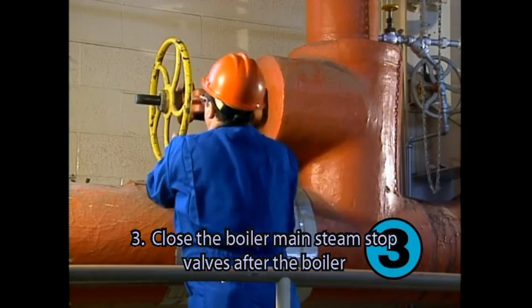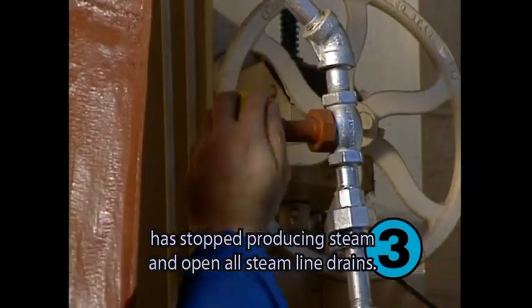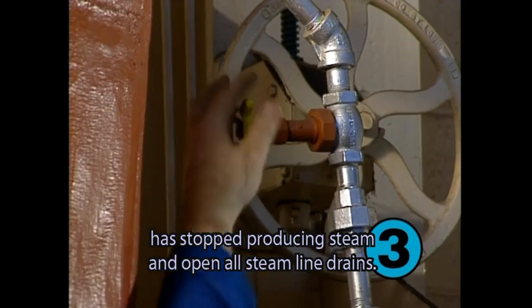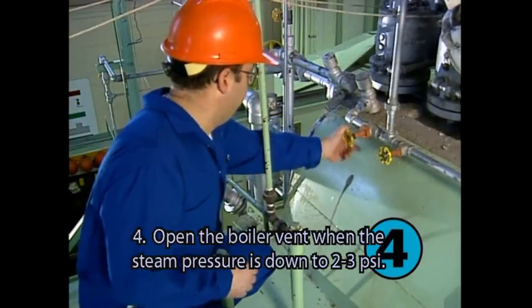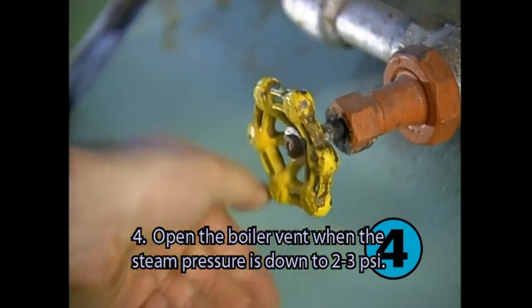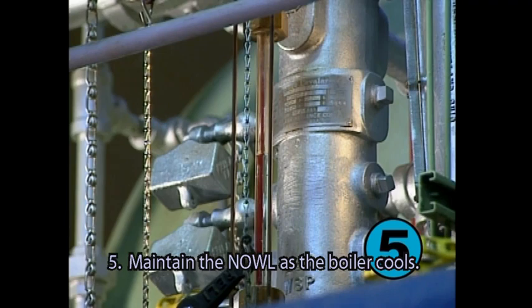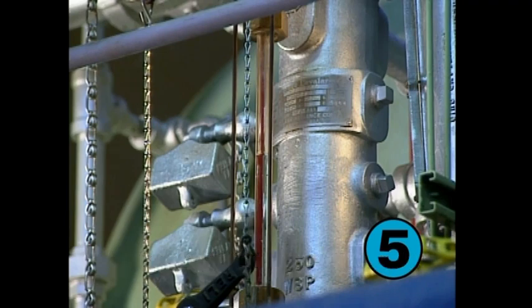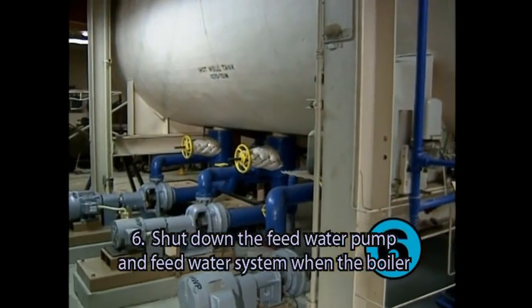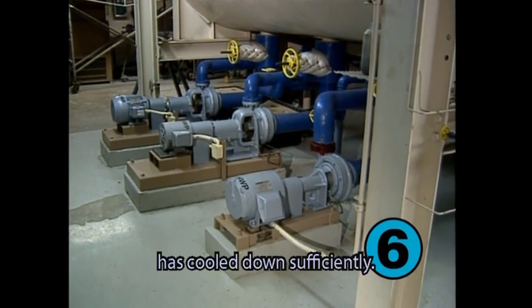3. Close the boiler main steam stop valves after the boiler has stopped producing steam and open all steam line drains. 4. Open the boiler vent when the steam pressure is down to 25 psi. This prevents a vacuum from forming in the boiler. 5. Maintain the NOWL as the boiler cools. 6. Shut down the feedwater pump and feedwater system when the boiler has cooled down sufficiently.